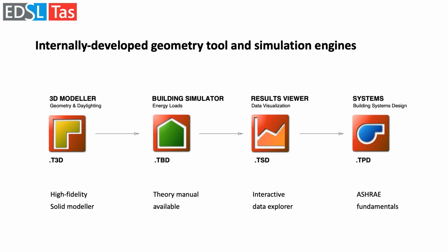The building simulator allows you to put all the rest of the building input information, occupancy profiles, the lighting controls, aperture types for natural ventilation, all the passive simulation and shading options, into here. You basically simulate the building loads, and then that goes into the results viewer where you get to review that data in a lightweight results viewer program, which in turn feeds into the HVAC program where you get to use template HVAC schematics, or even customize your own and build up, as it's component based.